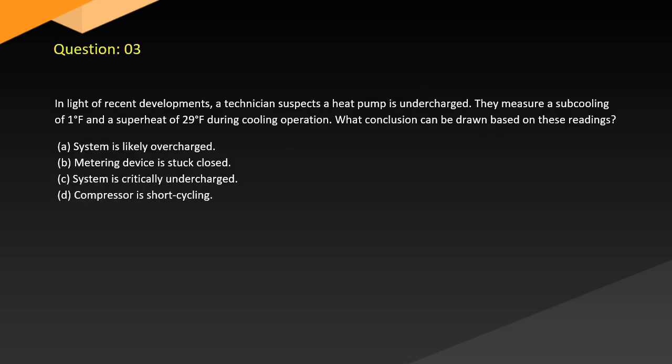Question 3. A technician suspects a heat pump is undercharged and measures a subcooling of 1°F and superheat of 29°F during cooling operation. What conclusion can be drawn based on these readings? A. System is likely overcharged. B. Metering device is stuck closed. C. System is critically undercharged. D. Compressor is short cycling.